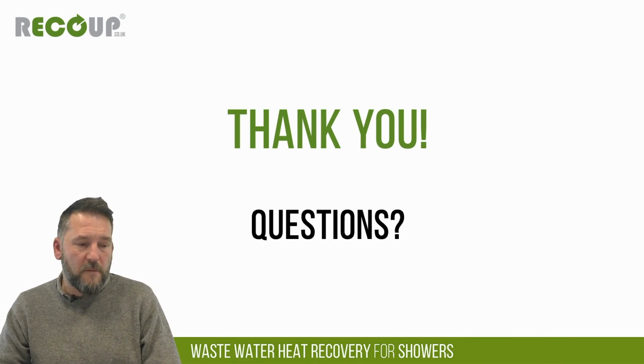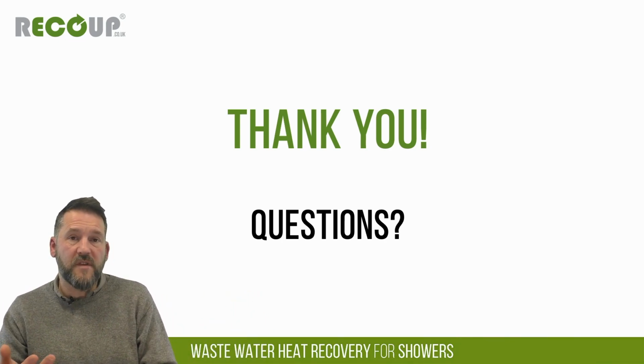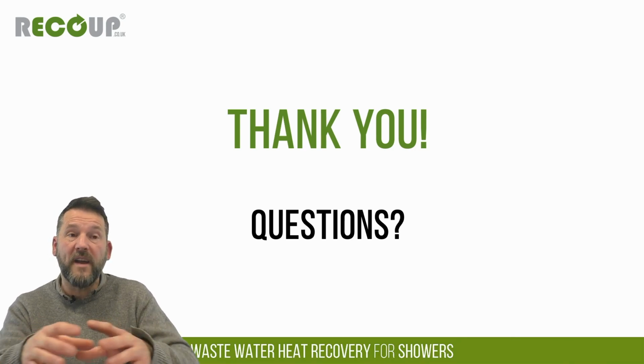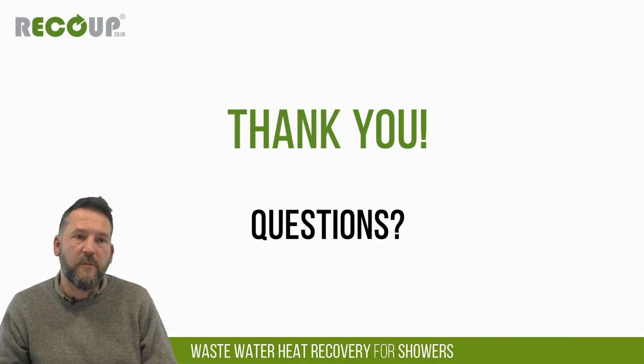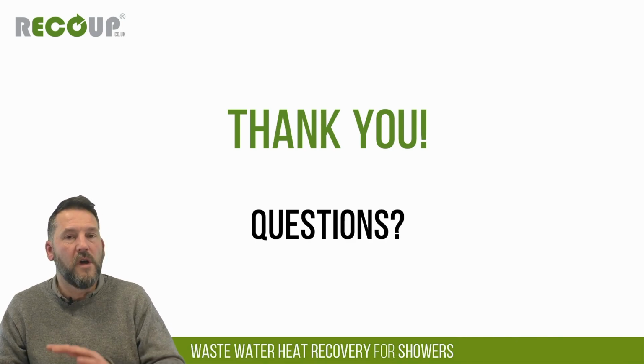On more commercial systems, with the drains on banks of showers, certainly 2 showers into 1 drain is very common. But if you've got banks of showers, 3 showers into 1 has been done previously. It will depend on the flow rate and how far apart they are in terms of the pipe work. But again, we can advise on that. But normally 2 in domestic settings and 2 or possibly 3 in non-residential communal showering environments.